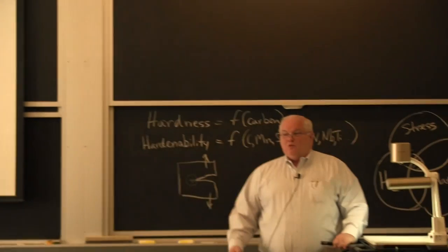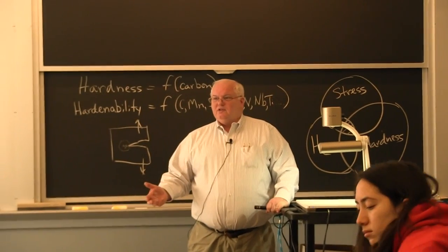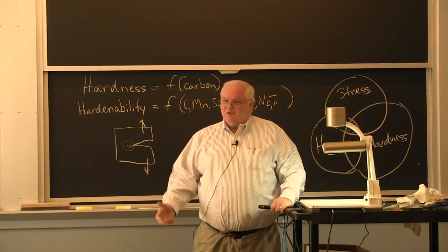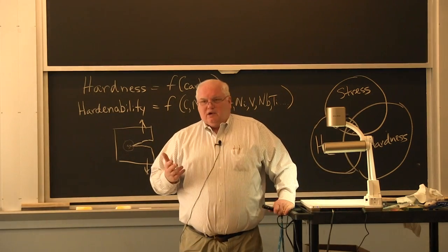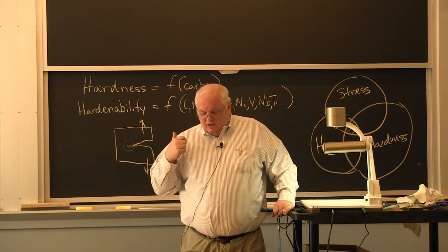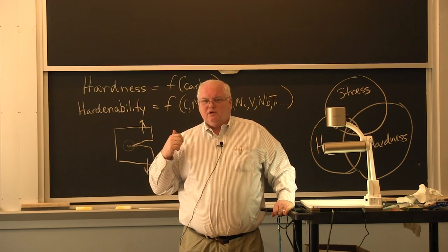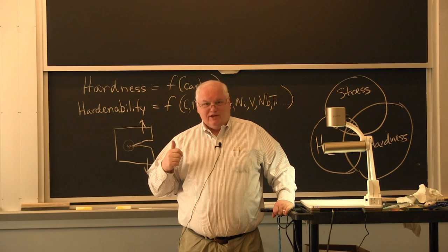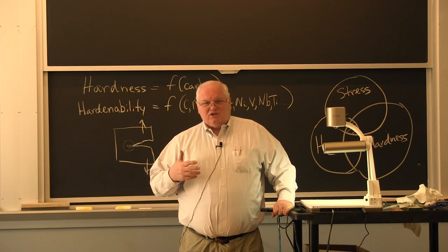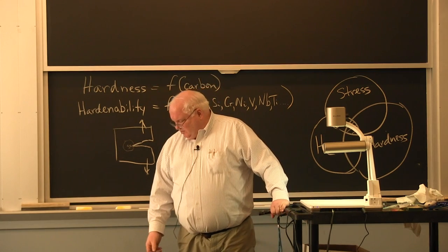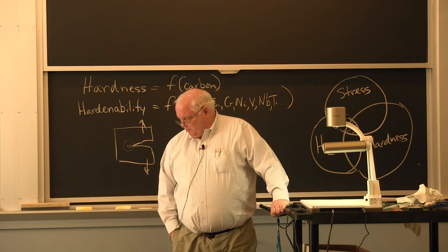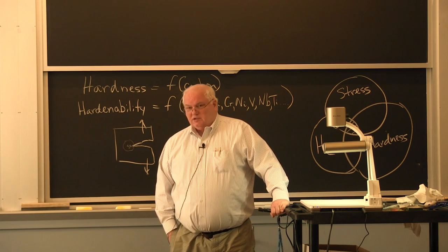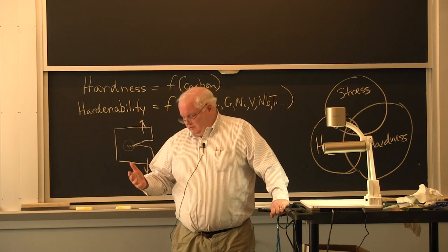Now, where does the hydrogen come from? What's the largest source of hydrogen in the world? Water, the ocean, okay? It doesn't come from the ocean, but it does come from moisture, because moisture's everywhere too. So it turns out one of the key areas is moisture. What also contains hydrogen? Hydrocarbons contain hydrogen, right? So any grease or oil that's around, lubricants. I can tell you a story about welding of the Seawolf submarine, and I tracked it down, in my opinion, to lubricants. The moisture can even be humidity in the air.